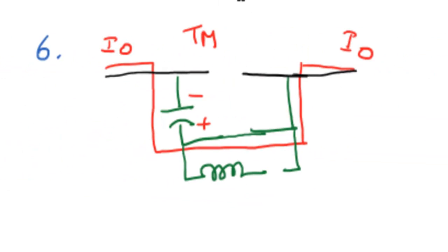Whenever you want to turn off the conducting thyristor, we need to turn on the auxiliary thyristor. You can see that the auxiliary thyristor anode is connected to positive, which means it is forward biased, so you can turn it on. Once you turn on the auxiliary thyristor, a sudden reverse voltage will appear across the main thyristor, and assuming everything is ideal, the main thyristor will be turned off. So that's what happened. Now the equivalent circuit is one where the main thyristor is turned off, and you can see that, as we discussed, the load current is still supplied by the capacitor and auxiliary thyristor.